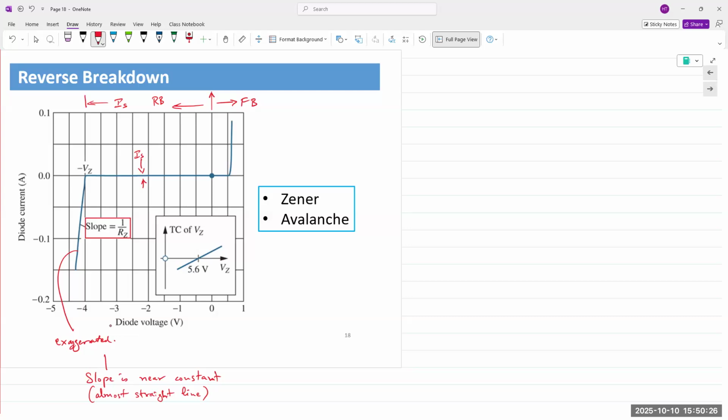And then there is something known as the avalanche effect. Not as sinister as it sounds. What happens in the avalanche effect is that the application of an external electric field, which is increasing in strength, imparts enough energy to many of these electrons that they are ripped from their bonds and are now free to move around inside the depletion region.